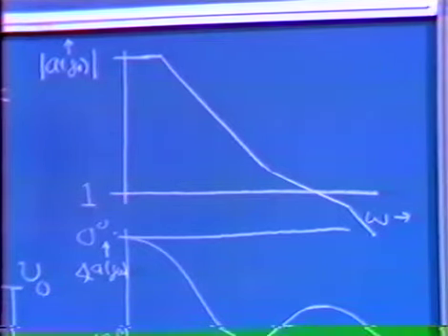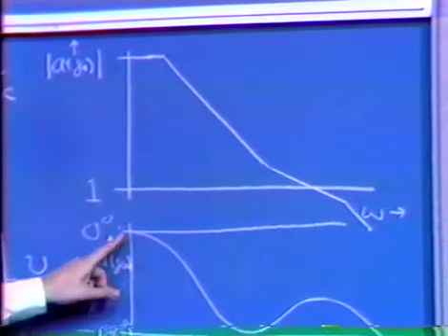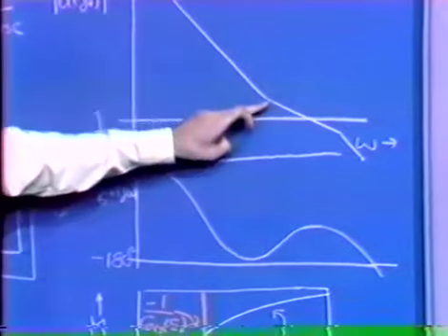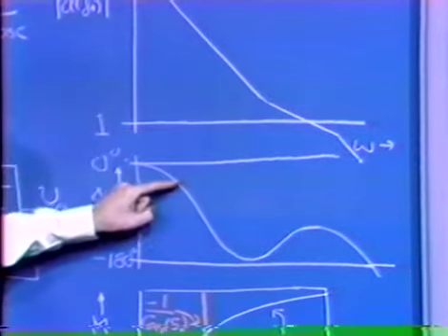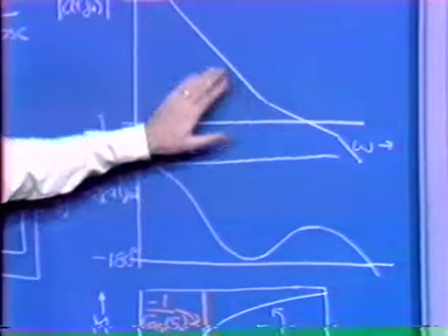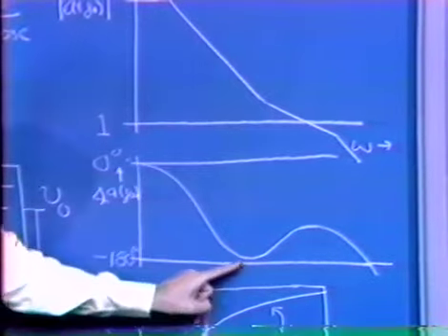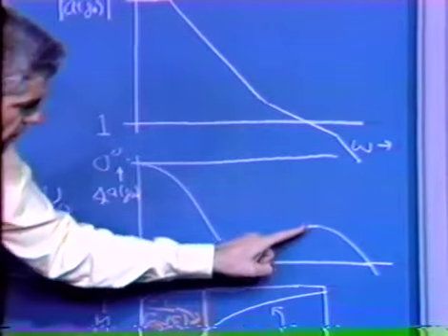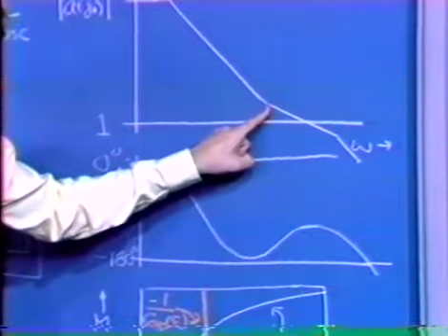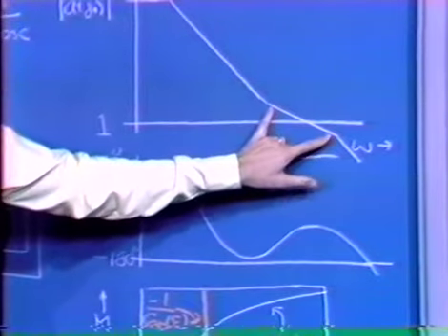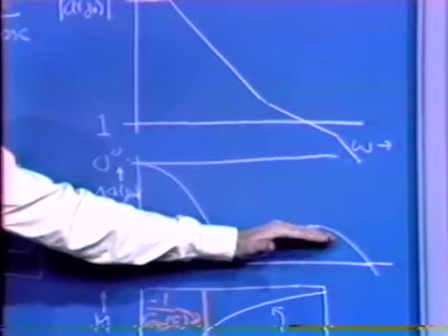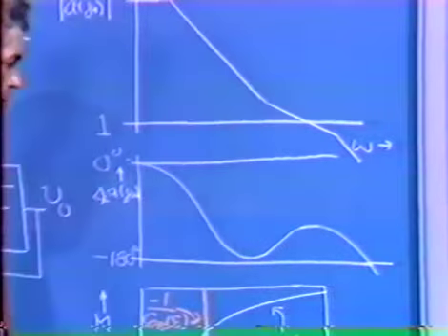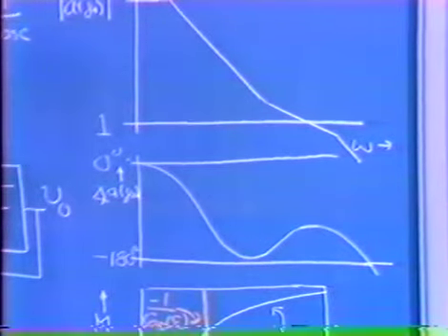The angle associated with that sort of transfer function, in this case, would start at 0 degrees. If there was a very long 1 over s squared region, the angle somewhere in that 1 over s squared region would drop down very, very close to minus 180 degrees. We'd then come back up, reflecting the 0 and the 1 over s slope. Again, depending on the duration of the 1 over s slope, we might approach minus 90 degrees in here. And then conceivably, the angle gets progressively more negative at higher frequencies.